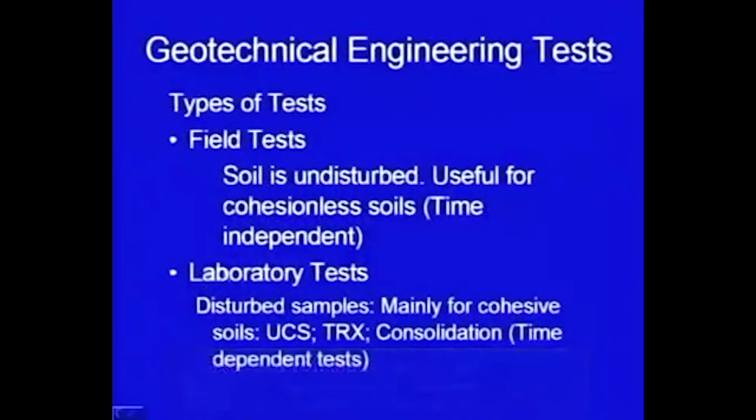Hello viewers, welcome back to the course on Foundation Engineering. Last time we had just started discussing the geotechnical engineering tests. There are two categories of tests which I discussed last time: field test and laboratory test. Laboratory tests are conducted on samples which are relatively undisturbed, and the tests are UCS, triaxial, consolidation, etc.